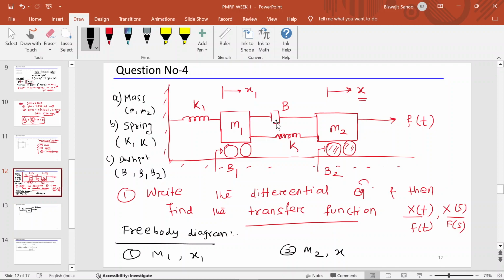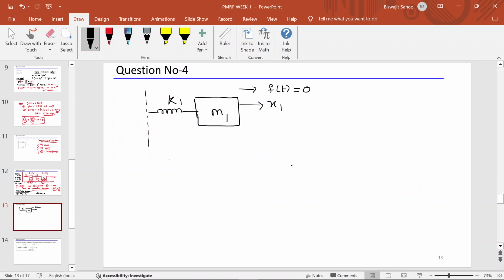Now, there is a displacement because these two bodies are attached, because of a spring and a dashpot. So I am dragging one, and automatically the other has a displacement, a supported displacement you can say. I'm not applying any force on it, but it is moving. So first of all, you need to identify what the external forces are. Here the external force for the body m1 is 0, but there is a displacement x1. Suppose now my body is moving to the right.